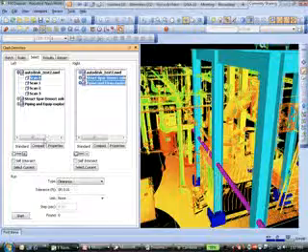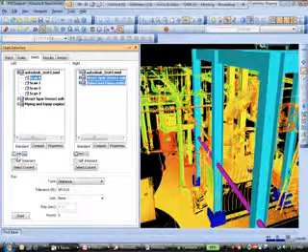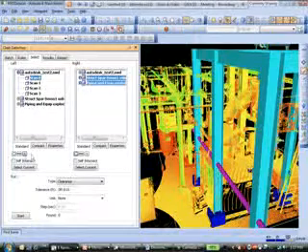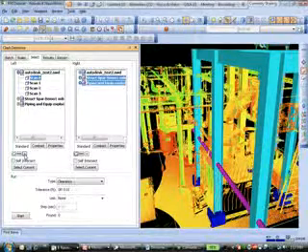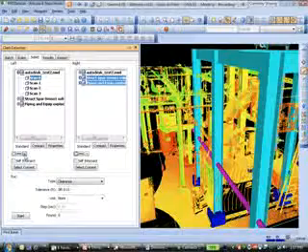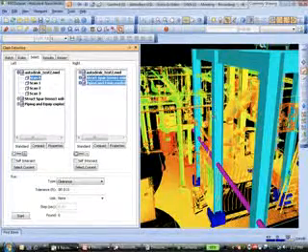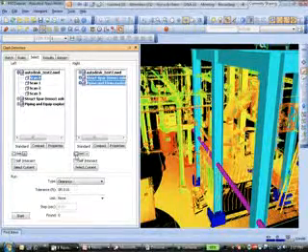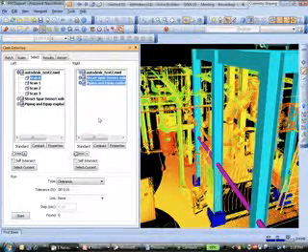And when I run the clash test, at the bottom here, it gives me a couple options. It gives me the surface, line, and point. On the point cloud, I want to recognize that as millions and millions of points on here. So I'm going to make sure that I have that selected. But I'm going to be clashing that against surfaces. So I'm going to have the surface tool selected for the right side of the clash.